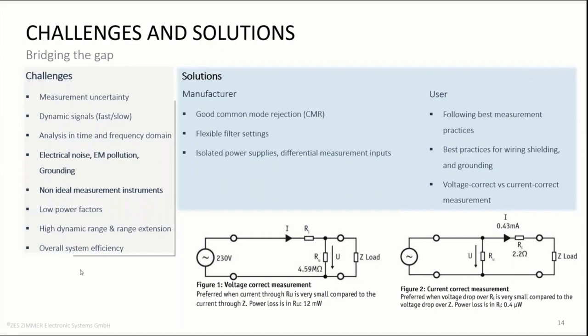Since both these currents are very low, as we are measuring a standby current, the part of I caused by the leakage current into the voltmeter will be comparable to the real load current, and the error of the current measurement or of the overall power measurement will be significant.